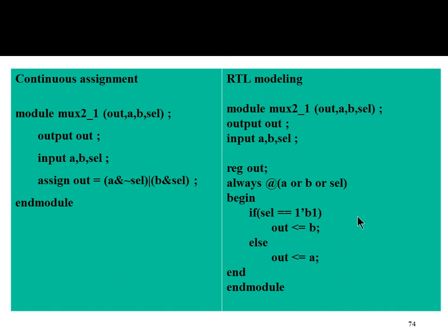With blocking assignments, you expect it to give an output with zero delay, and non-blocking assignments operate in a clock cycle. It's after the delta delay that it gets updated. So normally at the end of the always block, there is a delay involved.